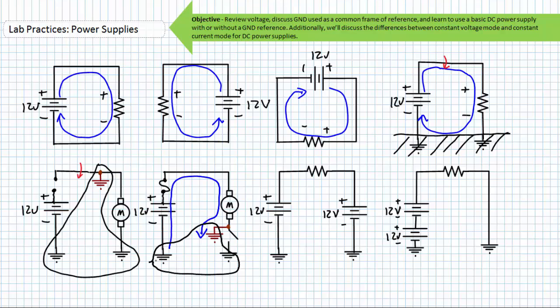The errant connection to ground is providing a path to ground for this motor, and the motor could start unexpectedly in a low side switching arrangement. Again, current is well within the operating parameters of this fuse, and the fuse will not blow. And a motor configured in a low side switching arrangement could unexpectedly start.